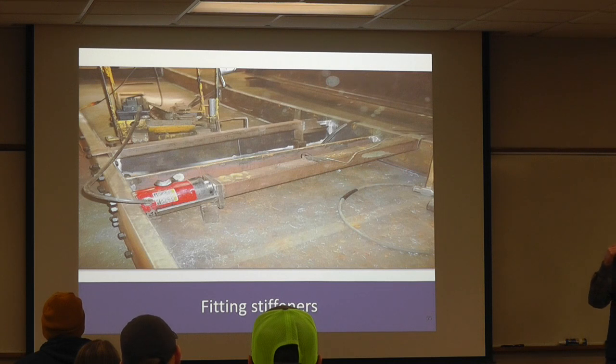Now these stiffeners are detailed to be a very tight fit. And so based on the shop drawings, these elements will get cut to within a 1/16 of an inch. Generally, they're cut ever so slightly longer, and because of that, oftentimes they'll have to go in and put a jack to slightly separate those flanges, drop your stiffener in, let that pressure off and weld it into place, because we want these to be that tight of a fit.